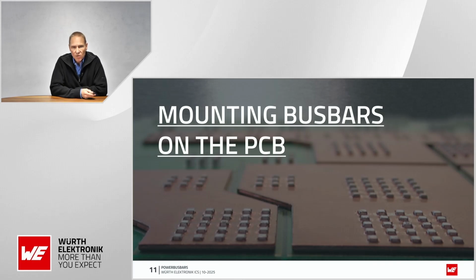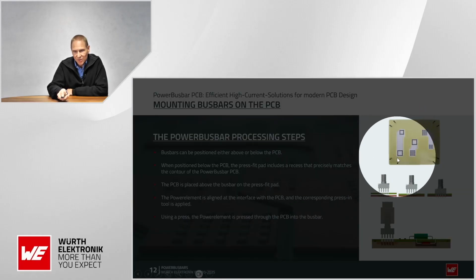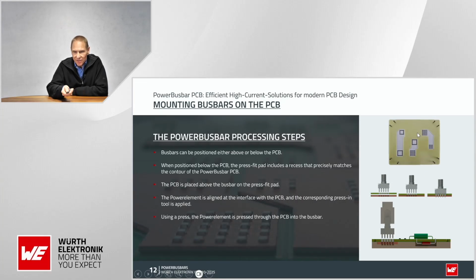Let us now have a look at how a bus bar is mounted on the PCB. The PowerBusbar processing steps are: at first you have to decide whether the bus bar is positioned either below or above the PCB. When it is positioned below the PCB, the press fit pad includes a recess that precisely matches the contour of the PowerBusbar. If the bus bar is larger, we can also add centering holes in the bus bar, and you can set centering pins in the press fit pad.